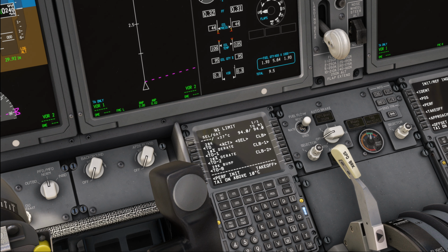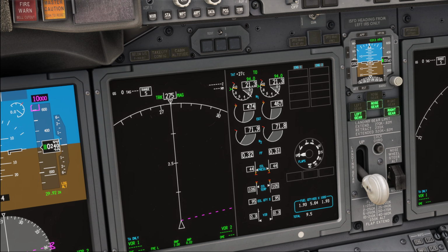The first is the engine electronic overspeed protection, which prevents a rotor overspeed from exceeding engine structural design limits both in flight and on the ground. If an overspeed event is detected, the EECs will shut down the engine.